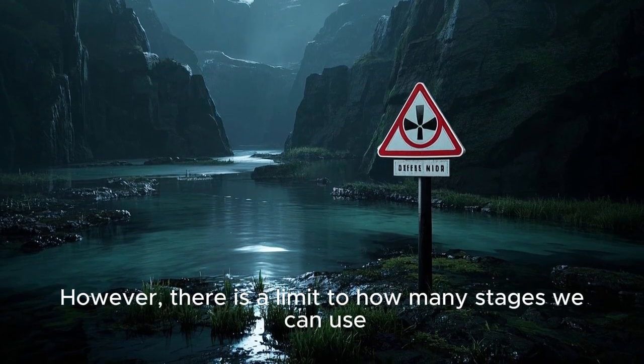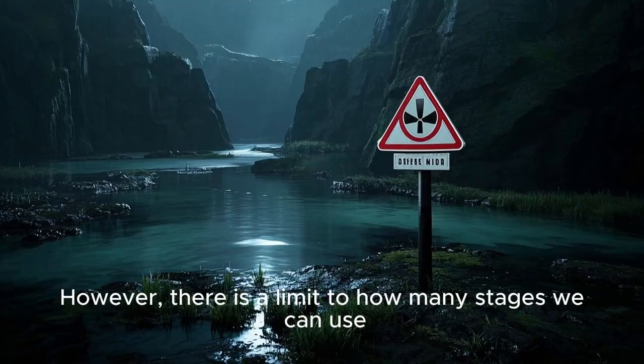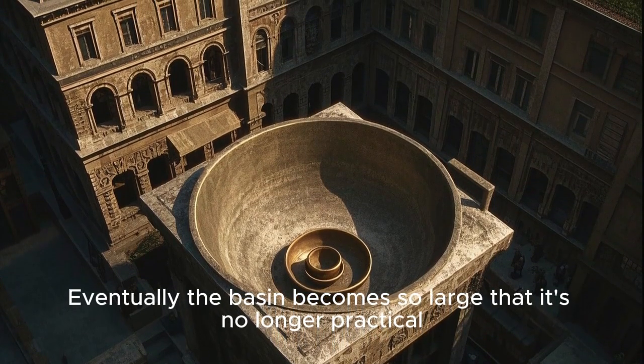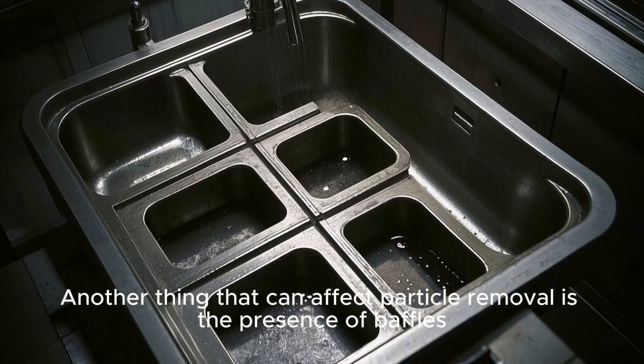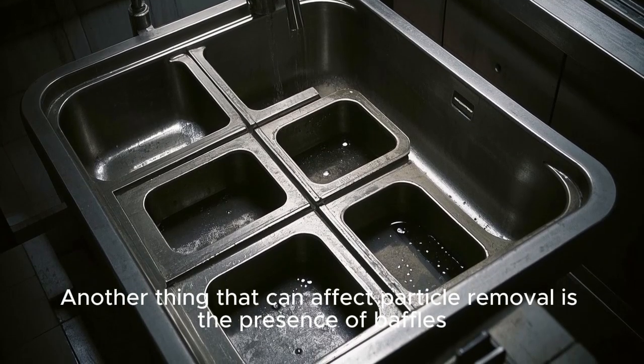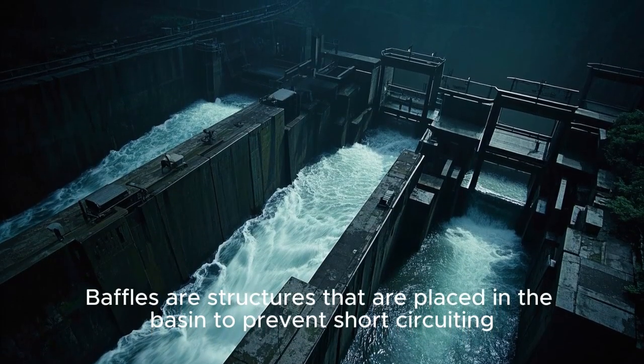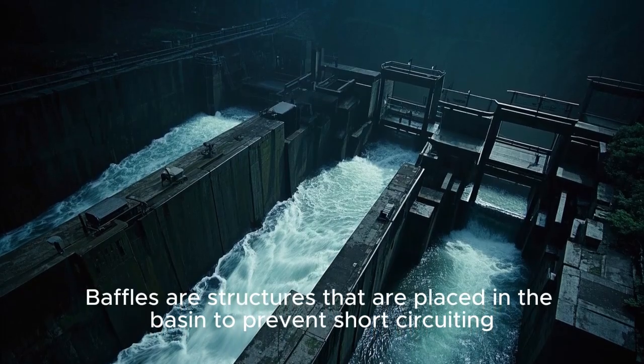However, there is a limit to how many stages we can use. Eventually, the basin becomes so large that it's no longer practical. Another thing that can affect particle removal is the presence of baffles. Baffles are structures that are placed in the basin to prevent short-circuiting.